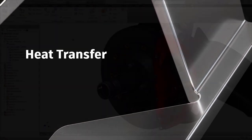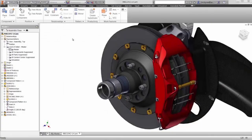Welcome to this video. We will show the thermal analysis capabilities of Autodesk Nastran in CAD. During this video, we're going to discuss the benefits of using steady-state thermal heat transfer analysis. Our eventual goal is to find if this brake assembly will fail due to high stress concentrations caused by differential thermal heating. We will focus on the rotor itself, so we can hide the other parts in the assembly.